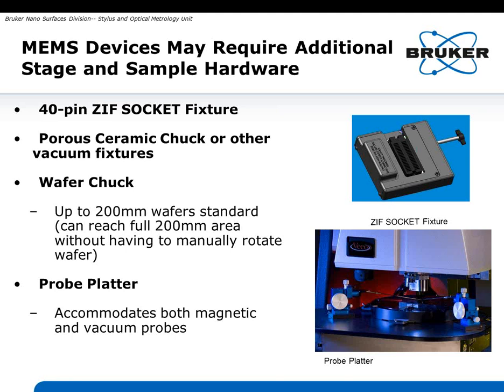frequencies. One thing I did want to just briefly mention is that MEMS devices often require additional hardware that should be considered when you're looking at metrology. What is the capability in terms of being able to handle the additional hardware, and is it sufficient? So it's easiest to test devices using ZIF sockets, so that's usually an important thing. The actual mounting of MEMS devices is extremely important for good characterization. So they're small devices, they are fragile devices.